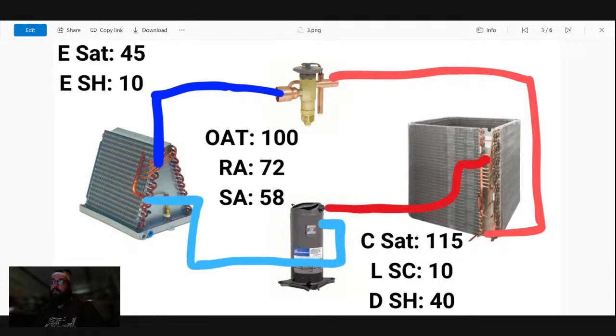Ultimately, if your evap superheat is maintaining, you're not having head pressure issues, and your evap saturation seems fine, but you're running elevated discharge superheat, it could be an oil issue. The oil is extremely critical to those compressors. It could also be a power issue. I don't know if maybe you're having a phasing problem. Something could be going on in the winding.